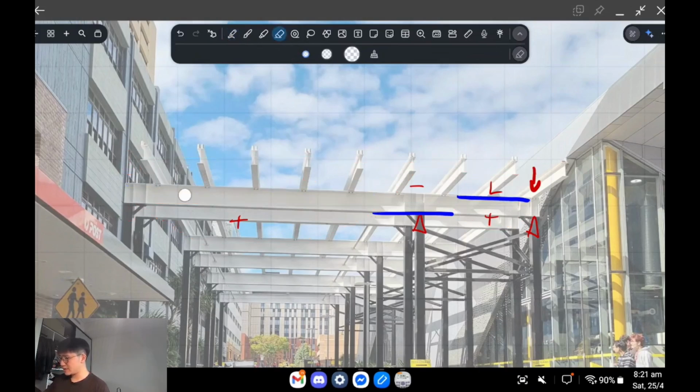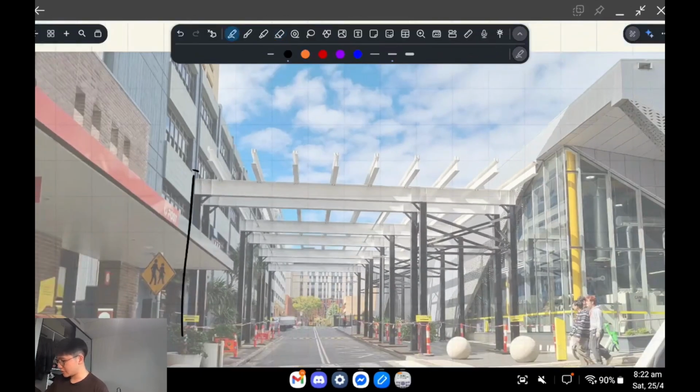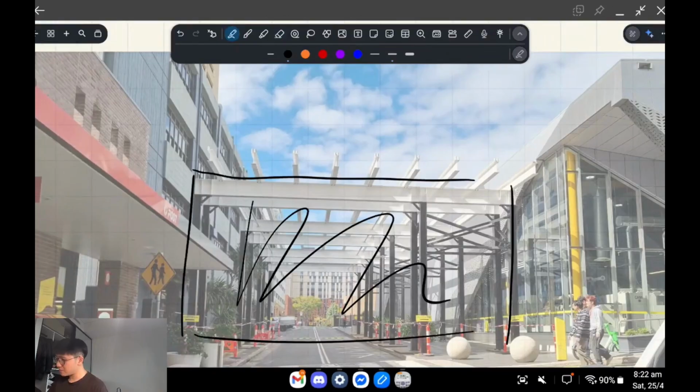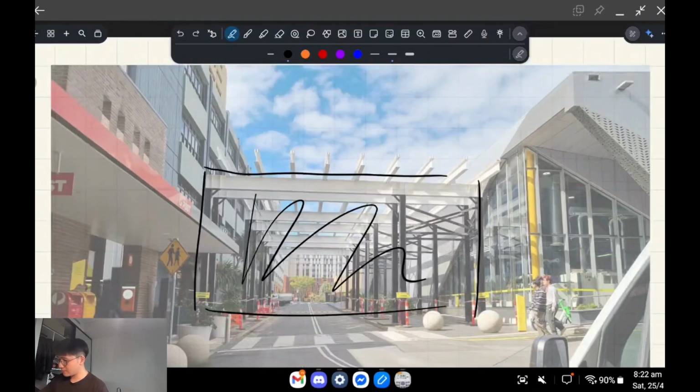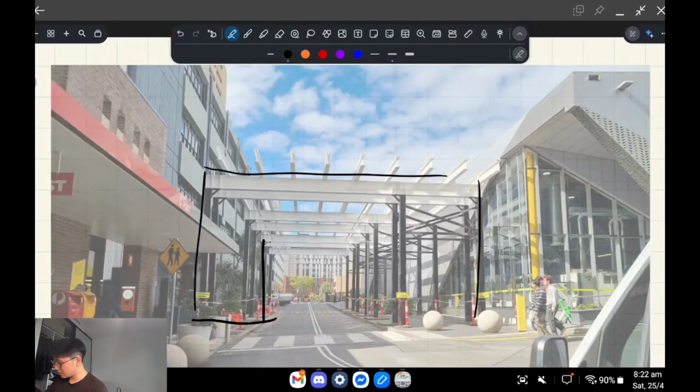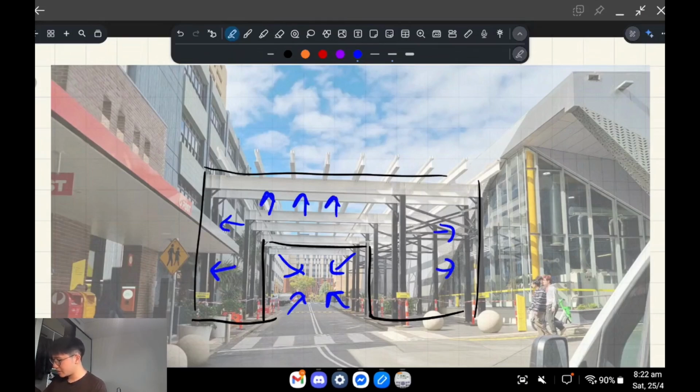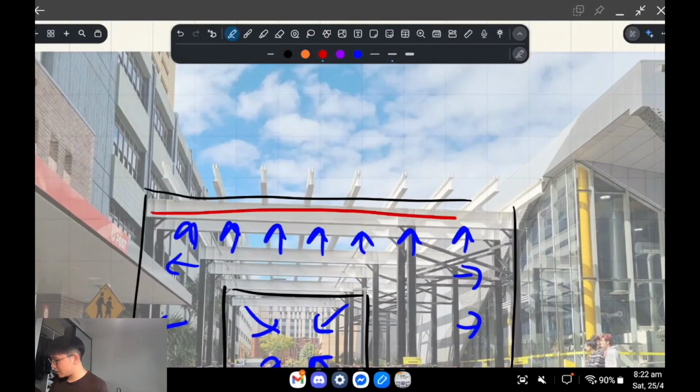If this whole building was, sorry, if there weren't holes everywhere, right? So there's sheeting on all these walls and stuff like that, right? And say there's a hole in this building, like a door or something, I don't know. Strong gust of wind blows in, okay? What happens is the pressure inside the building increases and it puffs up like a balloon. And all the surfaces from the inside want to expand out, including the top surface, right? And then in that case, this beam experiences uplift, okay? And then your bending moment diagram, when you factor in the dead load and stuff like that as well, might look something like that instead.